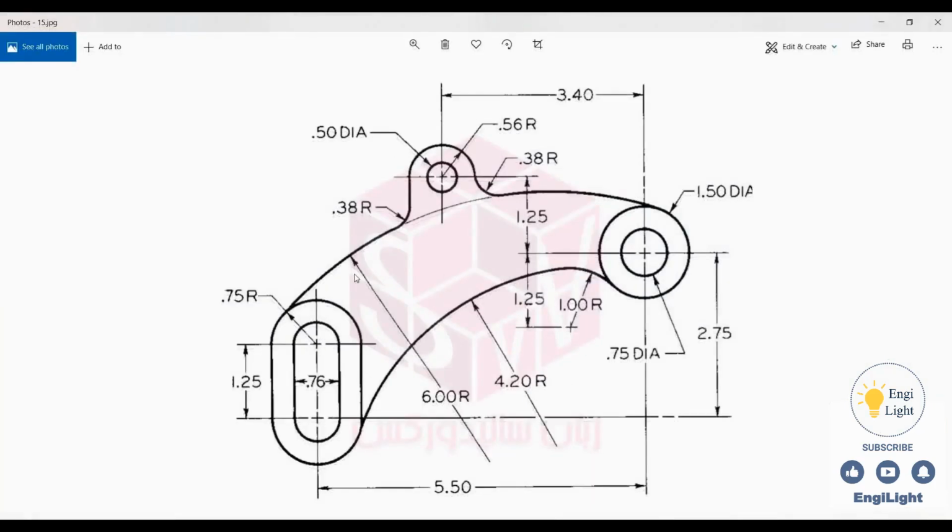Now for the upper section of the sketch, there's another arc with part of it trimmed. So I draw an arc with a radius of 6 inches here. From the second circle I drew, I create a straight vertical line from its semicircle to intersect the arc. Then from the intersection point I create a fillet with a radius of 0.38 inches.